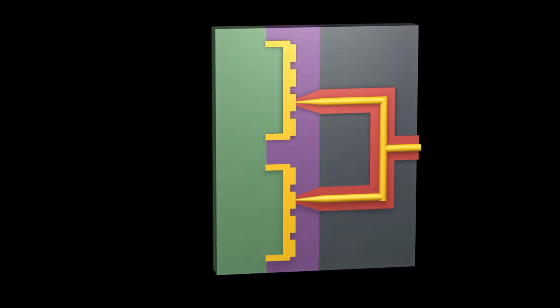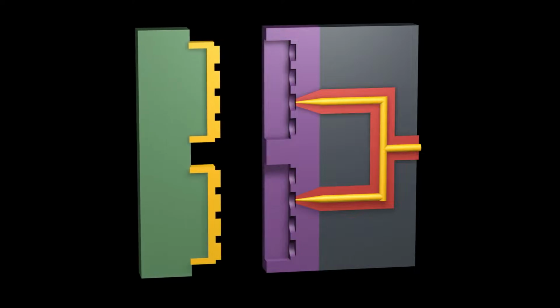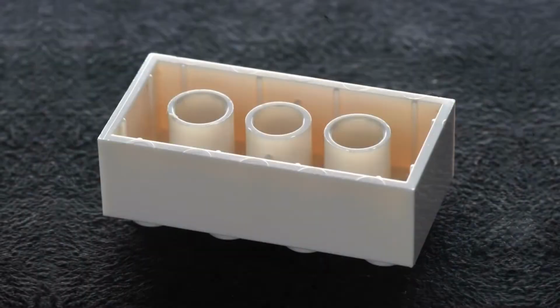This leaves no gates or sprues to be removed. The molded bricks are ejected, ready to use. The downside is that this setup is more expensive than a traditional cold runner system. On the bottom edge of the brick, you can see ejector pin witness marks. And what's most clever to me is where Lego designs their draft angle.